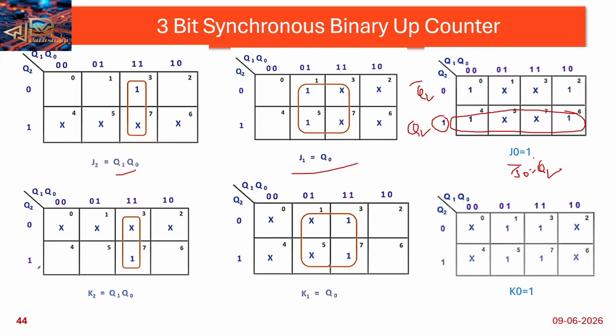See here, Q2 is there and another two ones are also there, right? So then another quadrant we can form. After that, all should be formed as octet. Then here, if you form the two quadrants also, that is Q2 bar. So Q2 bar plus Q2 is what is the output? One we will get. Clear?